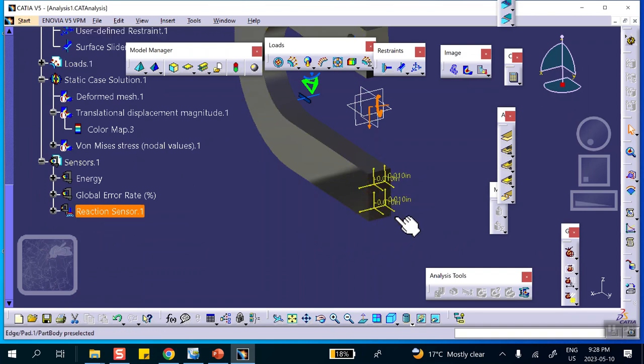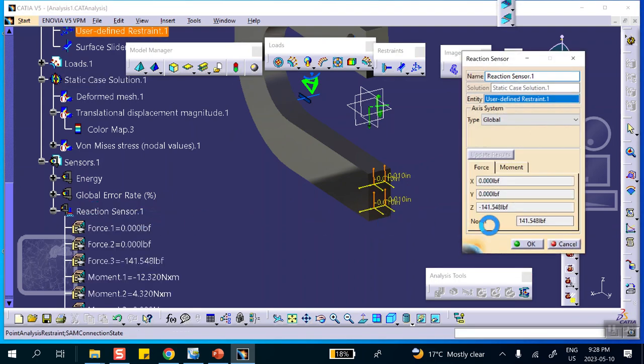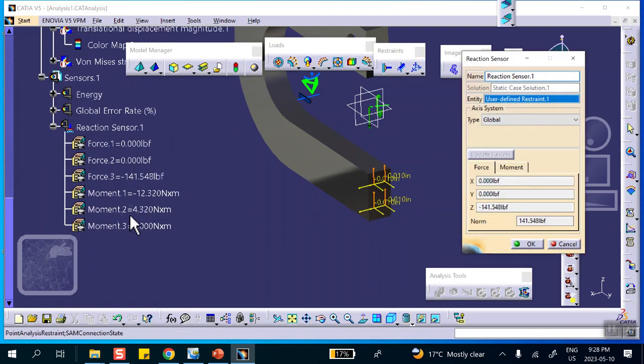So when you use planes of symmetry in a problem like that, the force is not what this is telling you. The force for the entire deformation, because there are two pieces you have to pull down. You're modeling half of it because of convenience, but the other half is there too. So you have to write double of that. So this is what I'm going to check in your tree. I'm going to check this, and I make sure that on your paper you wrote double of this. Okay.